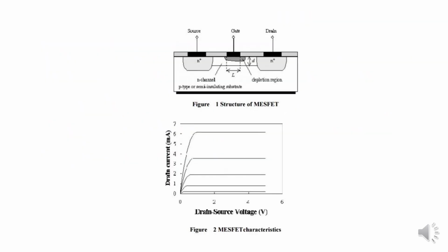Metal semiconductor field effect transistor. MESFET stands for metal semiconductor field effect transistor. Here it is quite similar to the JFET in construction and technology, and the difference is that instead of using the PN junction as a gate, a Schottky junction is used. The MESFETs are usually constructed in compound semiconductor technologies lacking high quality surface passivation, such as gallium arsenide, InP or SiC, and are faster but more expensive than silicon based JFETs or MOSFETs.